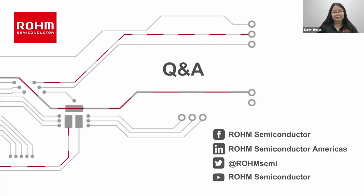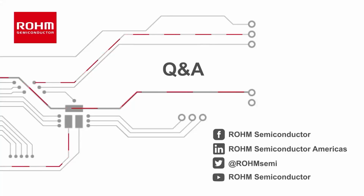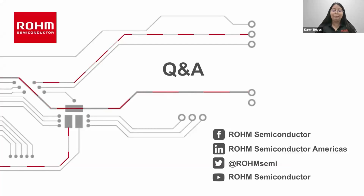Another question. How about the management system when you have more than one board? That's absolutely a great question. The BP35C5 is capable of managing up to 100 devices of the same BP35C5 working as a border router. We can also provide support up to 1,000 units, but this one will have to use a Linux device for the border router.